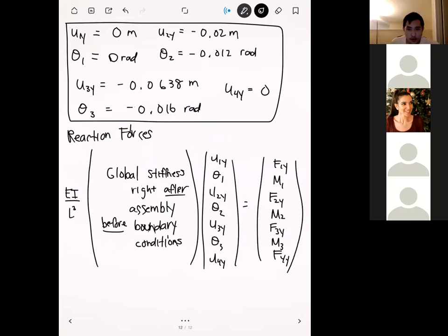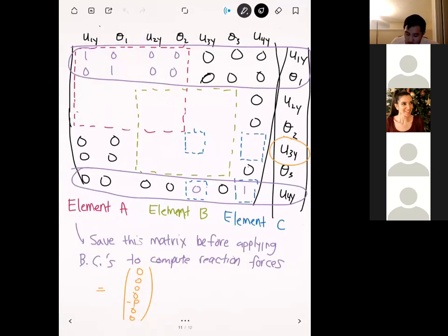Was there a question on this? Yeah, Professor, I have a question. Sure, what's up? In the case of the spring, the K, would you multiply times EI over L cubed, or where would the K go? Yeah, that's a good question. For the element stiffness matrix for the spring, we don't have the EI over L cubed, right? To cancel that out, what you'll see in the notes is I have this right here. So you have K L cubed over EI.